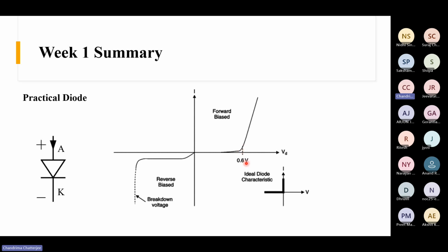So this is a constant voltage, but this is not the diode forward voltage drop, because this voltage will always be there. But as some current flows, there will also be some drop due to the resistance, right? That I mentioned. It's not only this voltage, but there will be some drop due to the resistance also, that comes due to this loop. As the current rises, you can see the voltage drop increases, right?